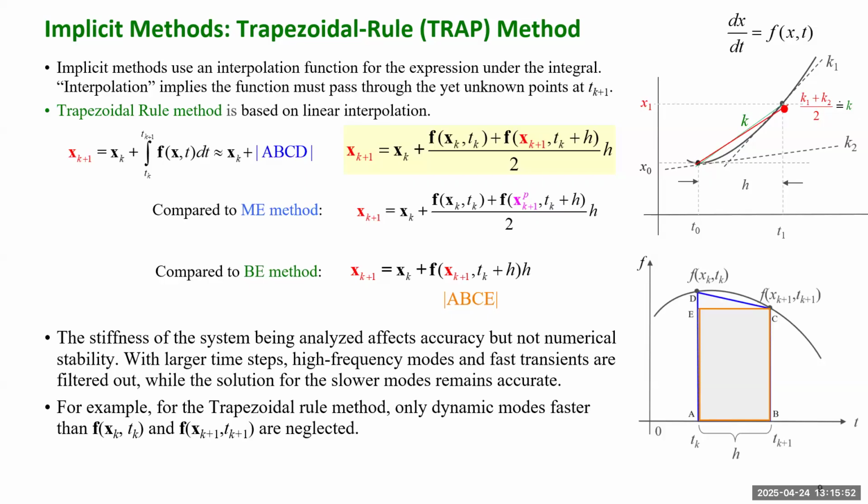If numerical stability is really your concern, which means you don't worry about the time cost to calculate the simulation result, you want to make sure you have a numerically stable result, and if the system is stable, the result won't be unstable. If that's your focus, you can choose the implicit method like the trapezoidal rule method.